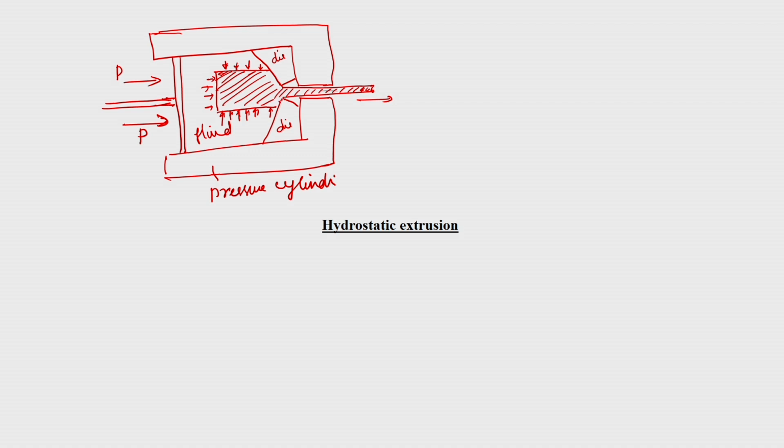The precaution you need is that at the interface of the die, the billet should be perfectly matching at the initial stage. Even if you seal it with Teflon tape, the fluid should not leak, that is one important condition which is required. If it leaks, only the fluid will come out, and there will not be any extrusion.